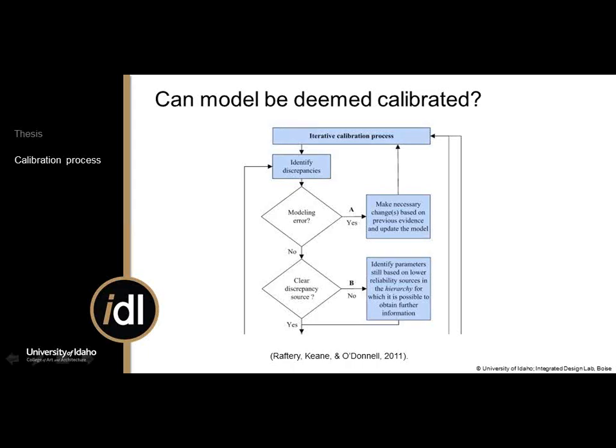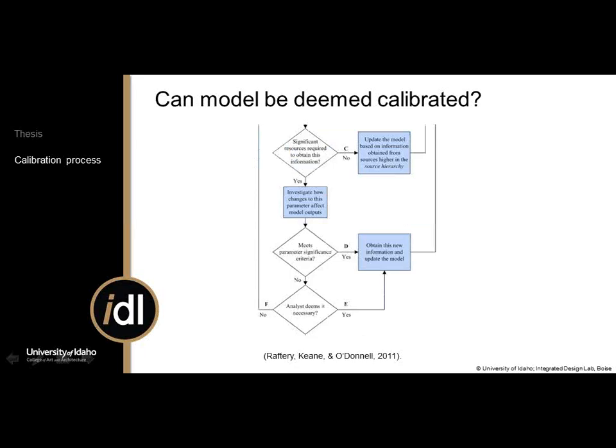So is there a clear discrepancy source, or is it a modeling error? Modeling errors can include a wrong weather file in the simulation, or the days that are defining the time frames for the simulation model. I've done that, where I want an annual simulation and the parameters are just set to do 1 month. So you've got to check out what the discrepancy is.